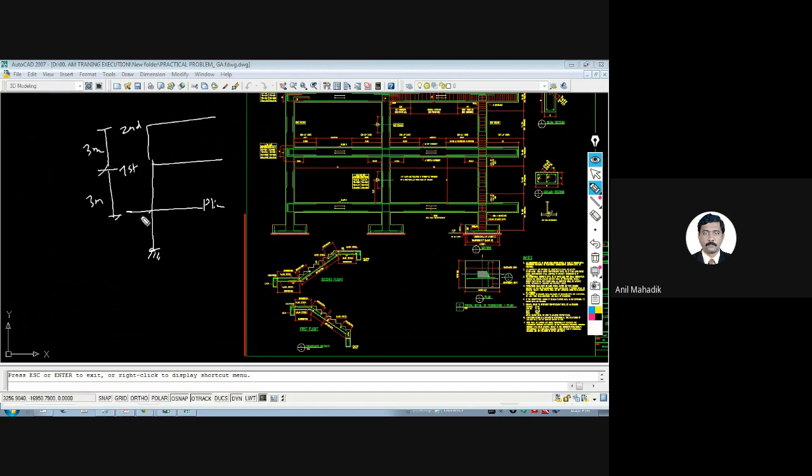And let's say you assume your hard strata is at a distance of 2 meters, for example. Then you also model this footing's supports in the ETABS model at 2 meters, and you design this column portion for a height of 2 meters, in RCDC or Excel, whatever software you use. But let's say you started the excavation and we found that our footing hard strata level is not 2 meters, but something like 4 meters. Suppose it is actually 4 meters in reality.